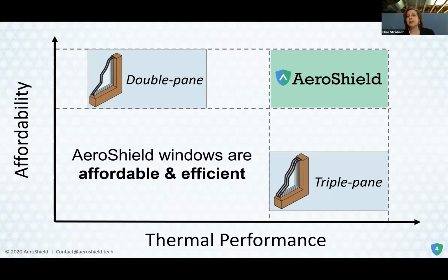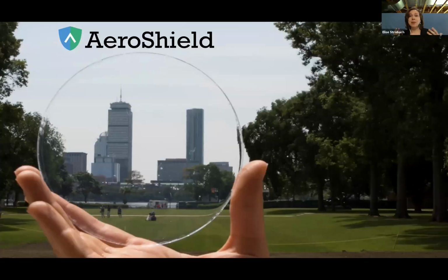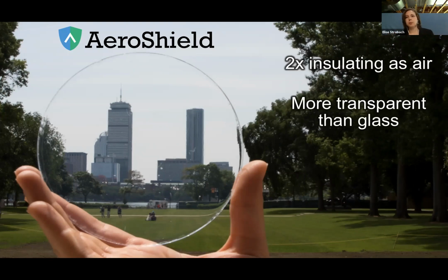that we really need to drive adoption of cleaner technologies. Now, the way that Aeroshield is doing this is by using an amazing material. So Jan nicely started to introduce some of this topic. Aeroshield makes a super clear aerogel. Now, when we look at the sheet, what you're seeing here is pure glass, but it's glass that's made up of tiny little pores, actually 95% pores, that are so small because we've engineered them to be smaller than the wavelengths of light, which means the visual experience is comparable to glass, but you get this amazing thermal performance.